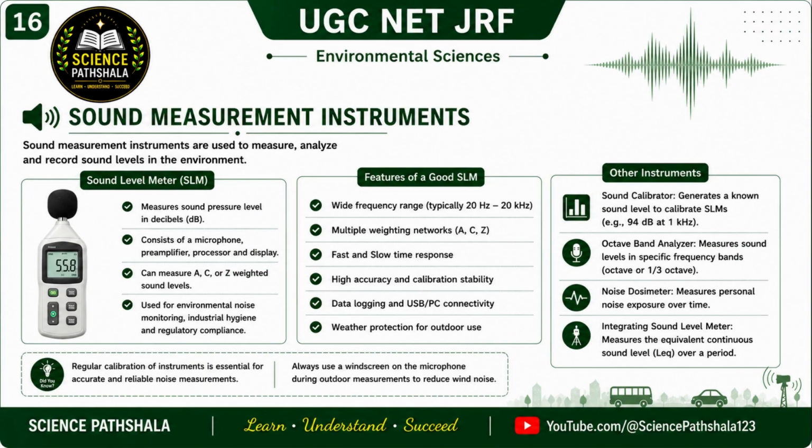Now next, let us study sound measurement instruments used in environmental noise analysis. These instruments help us measure, analyze and record sound levels accurately. The most important instrument is the sound level meter, commonly called SLM. A sound level meter measures sound pressure level in decibels or dB. It mainly consists of a microphone, preamplifier, processor and display unit. The microphone receives sound waves, the processor converts them into electrical signals, and the display shows the sound level reading.